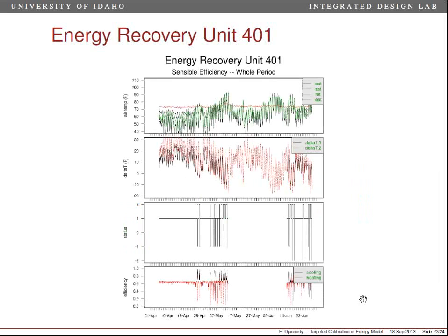presented the result. So this is the calculation of the actual efficiency, not what's on paper. We measure 4 streams of air and calculate the actual efficiency over time. We measured 4 streams of air: the incoming from outside, then the outgoing from the heat recovery, and then the return and the exhaust. We have 2 delta T here, and you see the status.